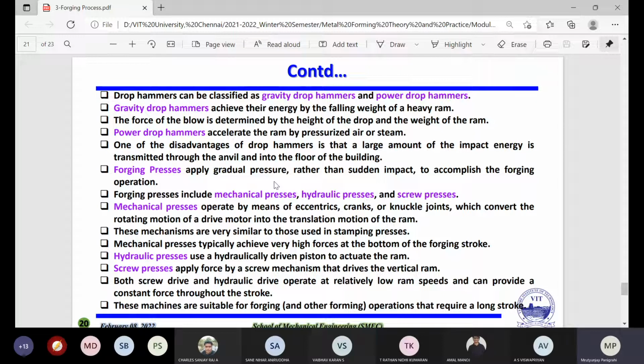In a normal furnace you cannot find that zone, because the thermocouple is outside the chamber, and the chamber is very big, so you cannot control the temperature there. You have to insert one more thermocouple near the sample. I told you this several times, so just remember it.